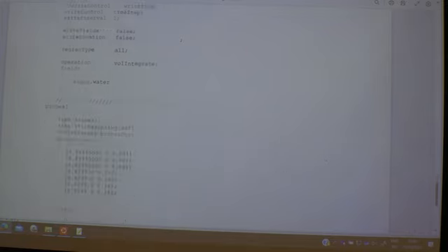So to show me the mesh, I would actually suggest you do something like this. Surface with edges. And then we rotate him, and then we can zoom in here. Zoom, zoom, zoom. Where is my zoom? Here we are. Maybe something like that. Just show me the bottom, and then I want to see how you have handled the mesh around this box. Okay? That's good enough.